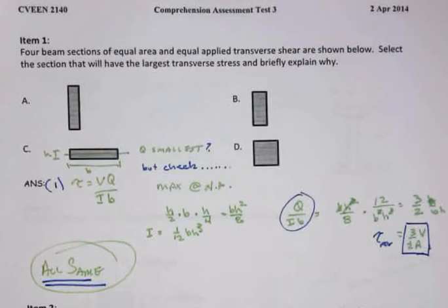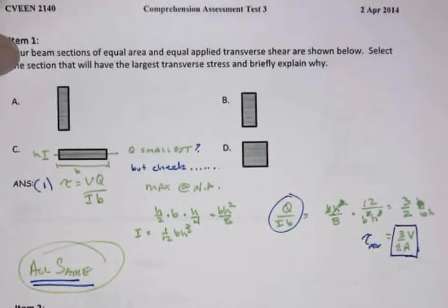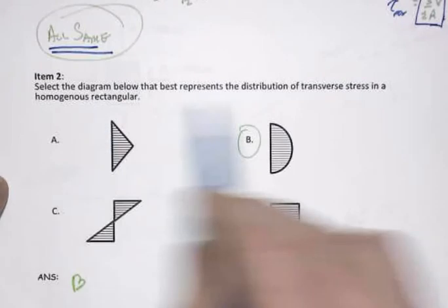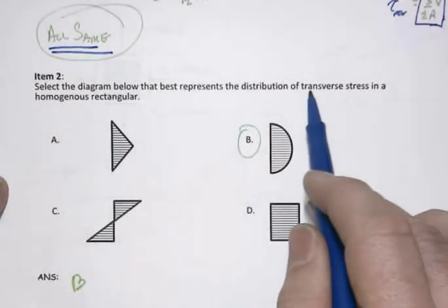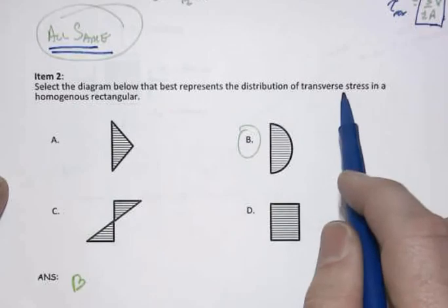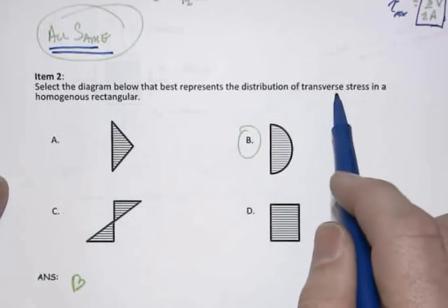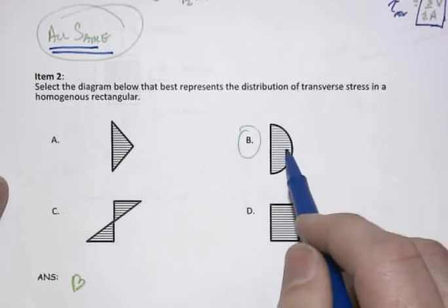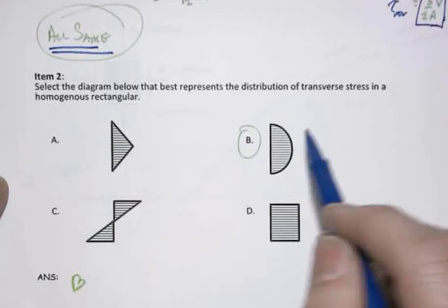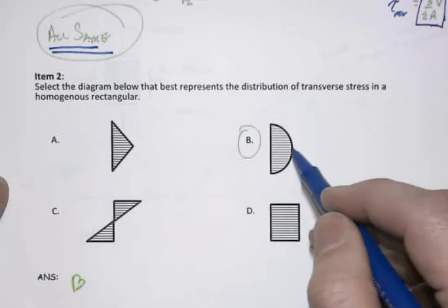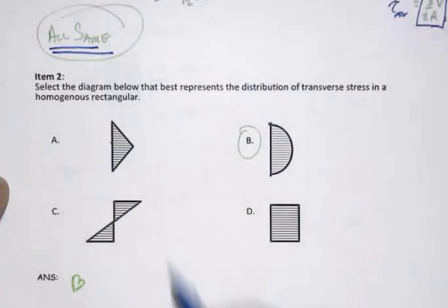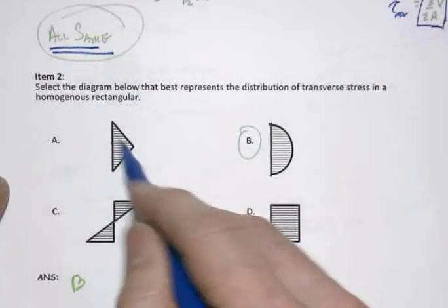We'll talk about how the partial credit worked on these problems in class. The second item actually has a little bit of poor grammar in there. It's a little odd. That's my fault, going a little too fast here. But the one crystal clear answer here, since transverse shear stress is what we're talking about through the first 3 items in this test, and that's a big item in this entire exam, is that we get a parabolic distribution of the transverse shear stress, 0 at the outer fibers. So neither C nor D can be right, and A isn't right because of the variation.